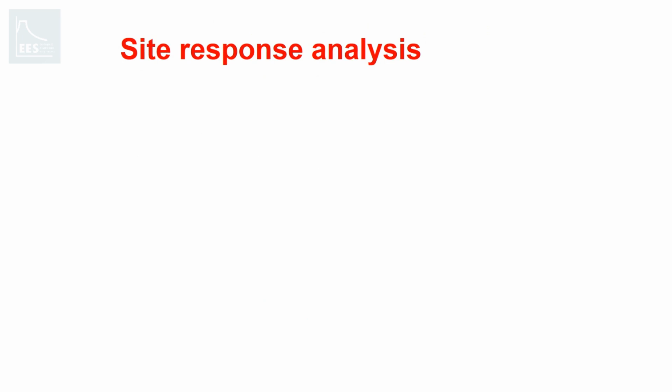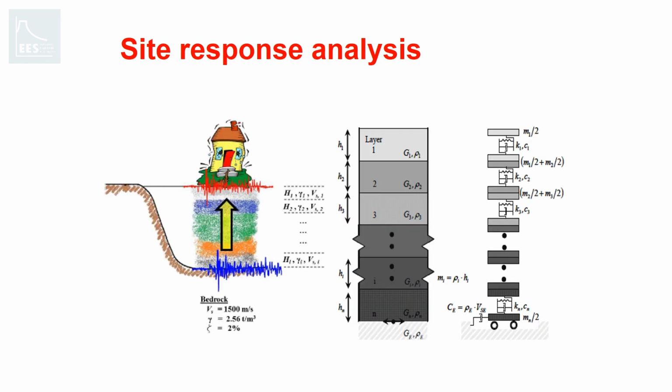As we have some background information about the PSHA and how it was conducted for Nepal, let's discuss site response analysis. Structures are located at ground level, which is at a level above the engineering bedrock, and there can be different strata of soil, and these can act as a filter to modify the properties of ground motion recorded at the bedrock. They have the capacity to modify the intensity, duration, and ground motion frequency content.